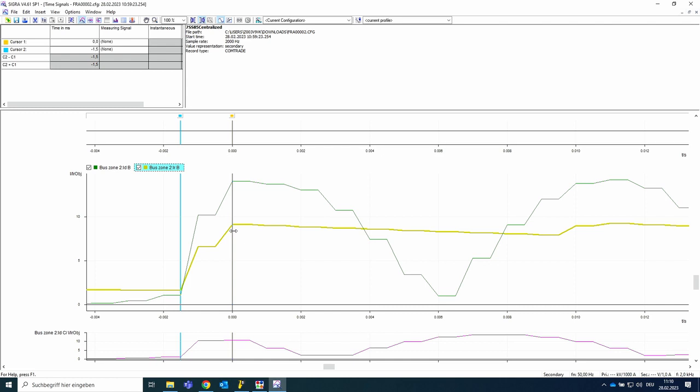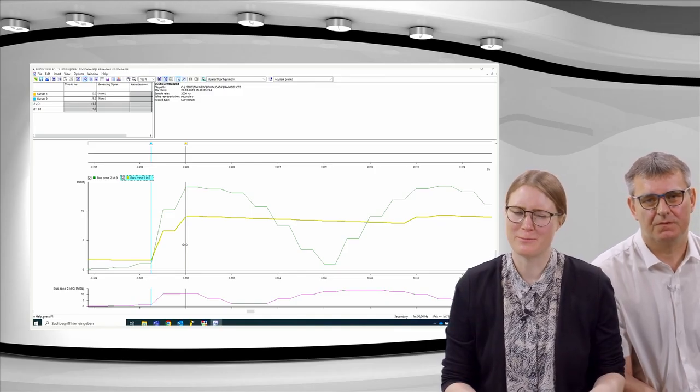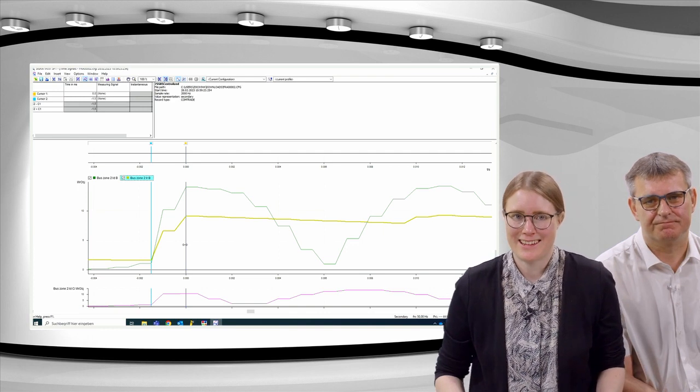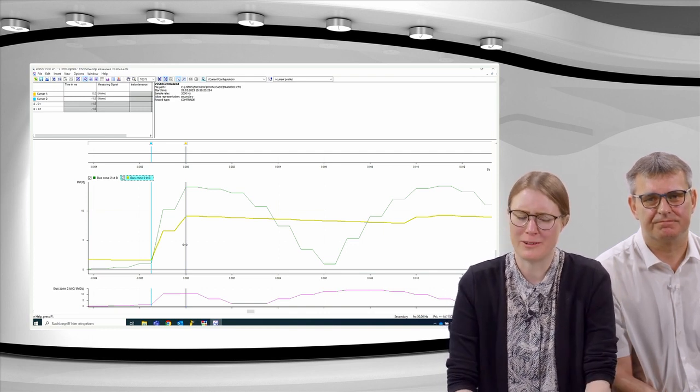And from the fault inception, that's here at the blue line, around the fault inception, to the black line, that's 0, that's the tripping. Of course, the tripping of the algorithm without the delay of the binary inputs. So the algorithm has seen this tripping within 1.5 milliseconds in this case. Okay, and this is happening with the 1-out-of-1 algorithm, and this is why I called this test case internal trip 1 minus 1.